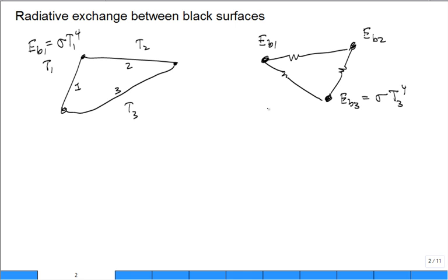And what do we have that would allow the flow of radiant energy back between these two surfaces? Some resistances. And what were those radiative resistances? They were the geometrical, R_GEOM is what I like to call them, geometrical radiative resistances, 1 over AF. So if you're going from surface 1 to surface 3, it's 1 over area 1, view factor 1 to 3. Or you could put 1 over area 3, view factor 3 back to 1, either way. But in general, it's always the same form, the geometrical radiative resistance 1 over AF.